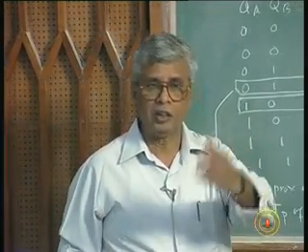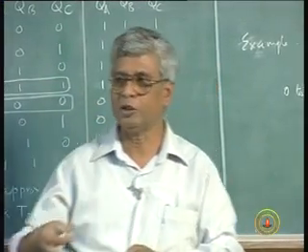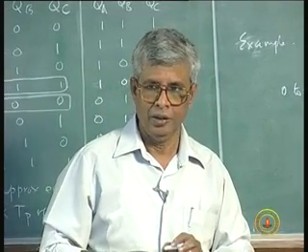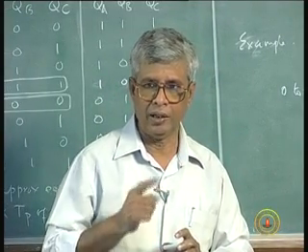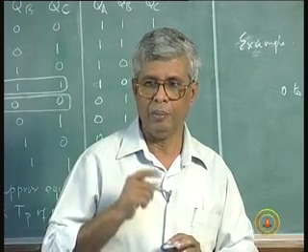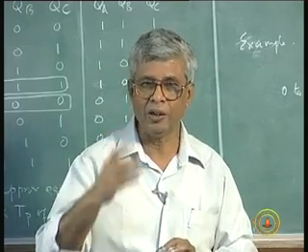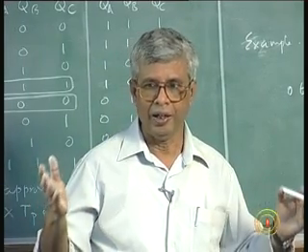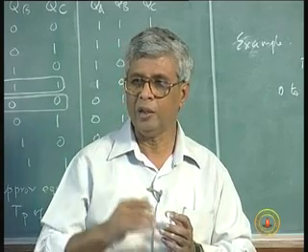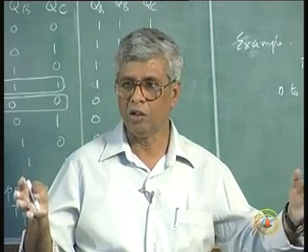Now if we are talking of these clocks, the watches I told you just now, from 3.6 megahertz you have to count down to a second, right. 1 hertz is 1 cycle per second, which is 1 second, and megahertz is 10 power 6 times 3.6. So 3.6 million to 1, you will have to find out the number of flip flop stages required. When that is the number of flip flop stages required, each count is going to take that much longer to materialize,